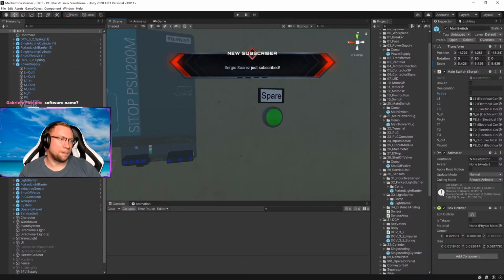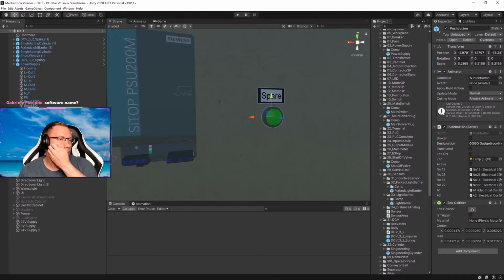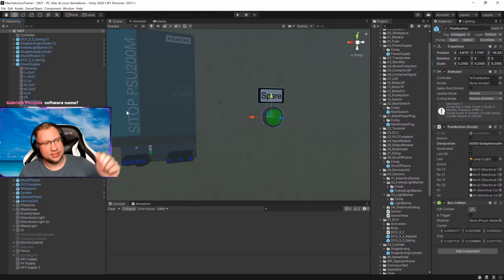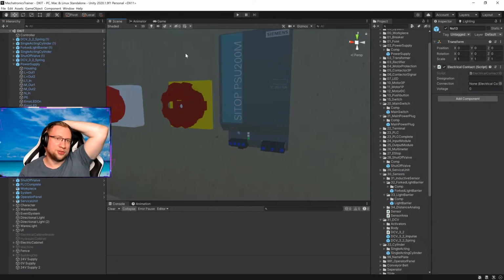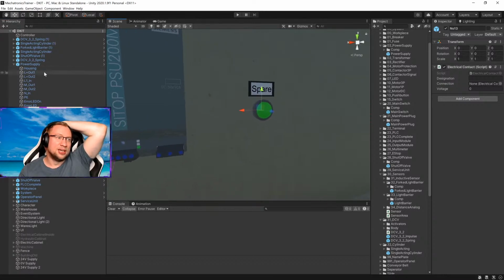So, okay, power supply works. Next. The push button. I want the push button to connect from the power supply to the DCV. So, NO13. Yeah, normally open contact number 13 is connected to 24. So far we have 230 volts. This makes 24 volt out of it. 24 volt output from here connects to the push button. Input number 13 here. So L plus out. Power supply, yeah, L plus out connects to the button.